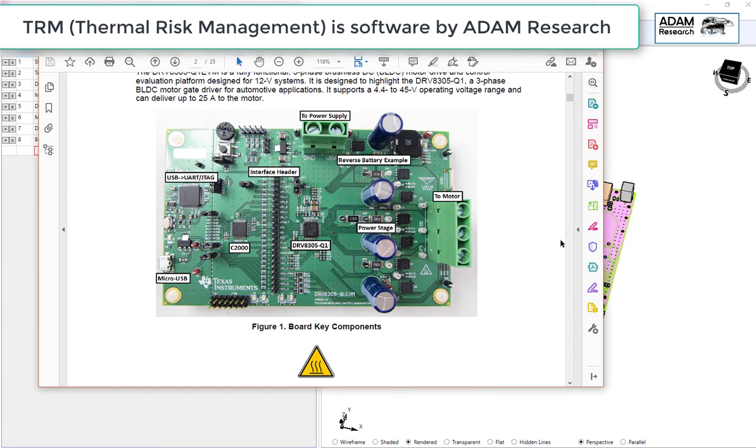It looks like this. We do not treat the logic part, we only treat the power supply part. And we focus on the power stage, which is the MOSFETs and the shunts. The flow of current is assumed to be a DC approximation. We start at VBAT and follow the traces through the low and high side MOSFETs and the shunts, and then return the current from here to ground.